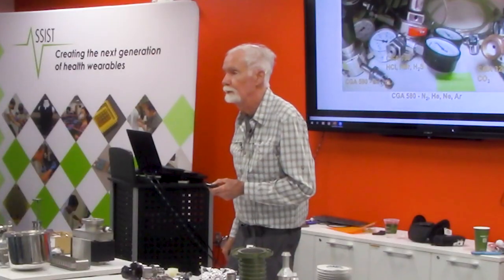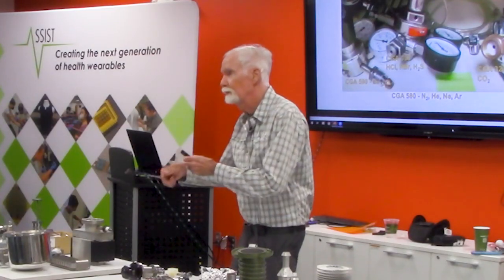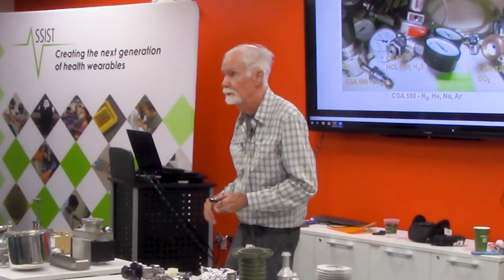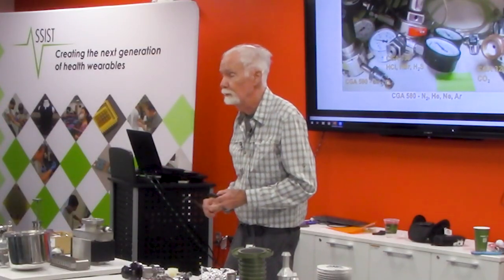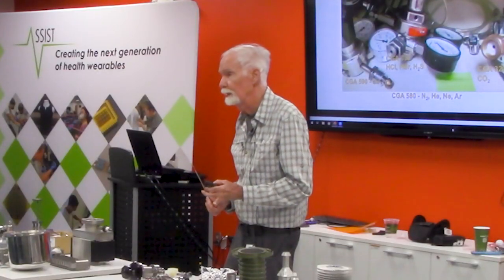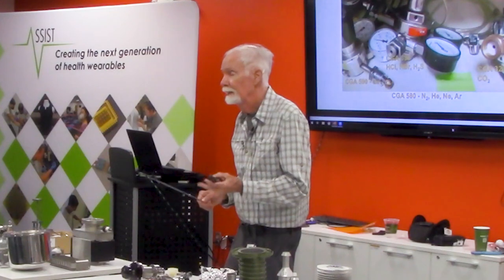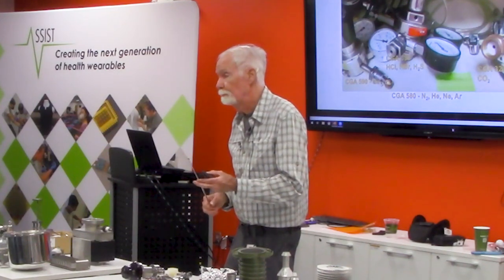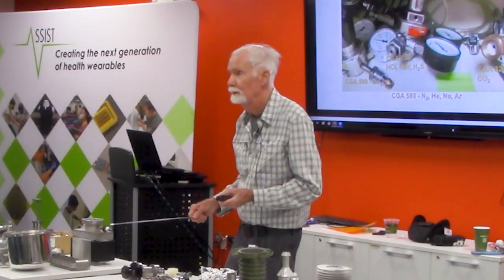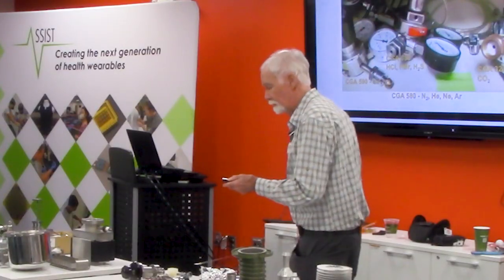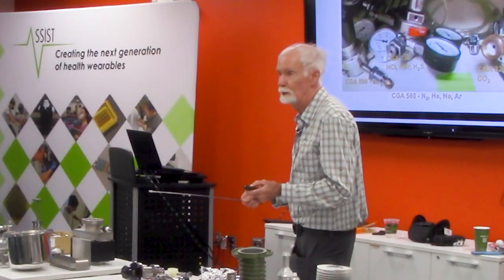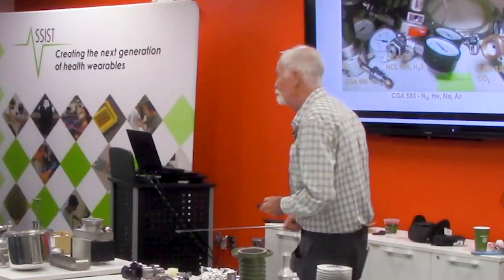You only have so many configurations you can use. You've got so many different gases, so many regulators. I think that was the main reason. Two reasons. One is, in some cases they said, this is better for a nasty gas because you won't be able to put it on. And number two, there are only so many fittings. So now if I do left-hand thread, I can have the same fitting in left-hand and right-hand thread. But take a look at the list. And for lecture bottles, there's another whole set of them.